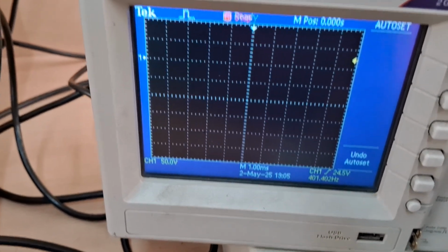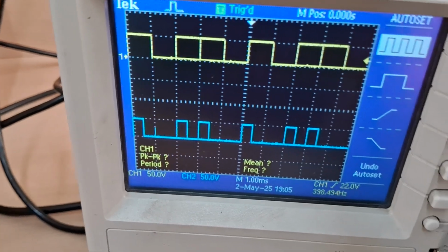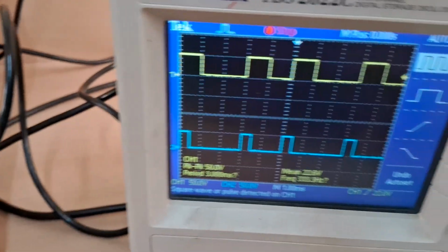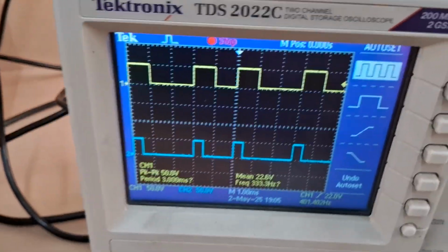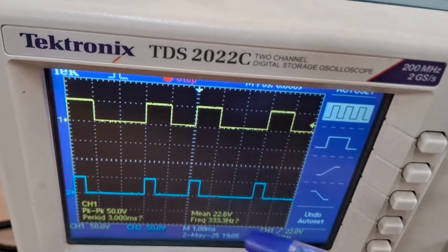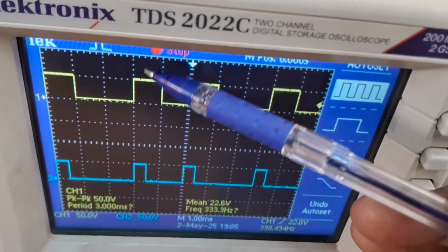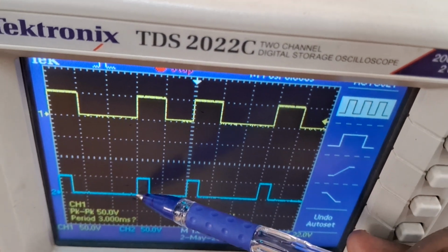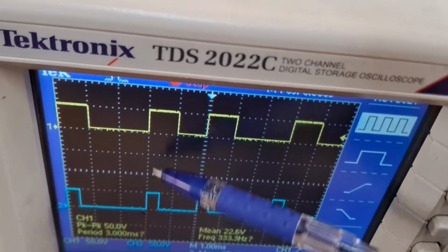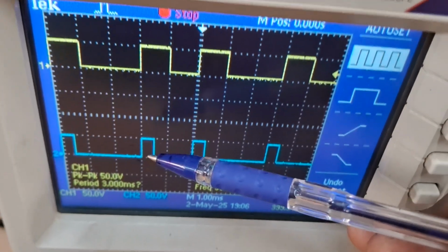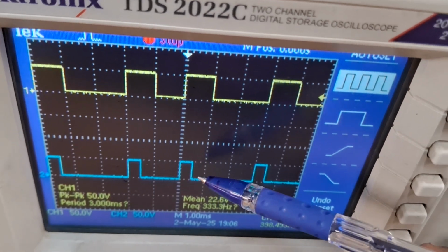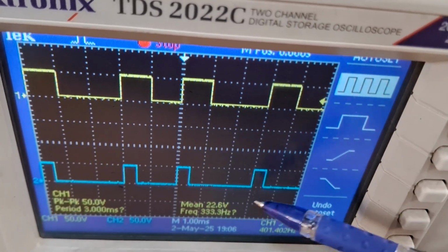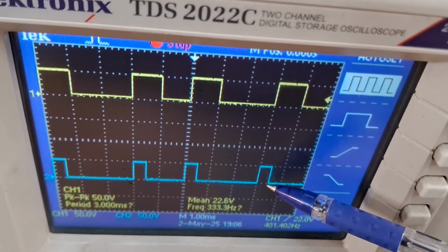So see, what you have is the waveform. Let's observe the waveform. Right. So what does the waveform say? See, as I said, it is a return to 0 format. So in between the logic 1s, the format returns to 0. Here you can see the format returns to 0 in between. So logic 1 lasts for TB by 2 duration. For 0 it is 0. Again for the next one it is TB by 2 it is 1. Next 0 it is 0, and again for TB by 2 it is logic 1.